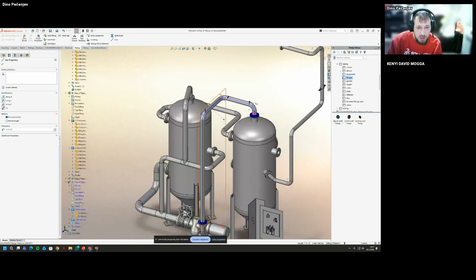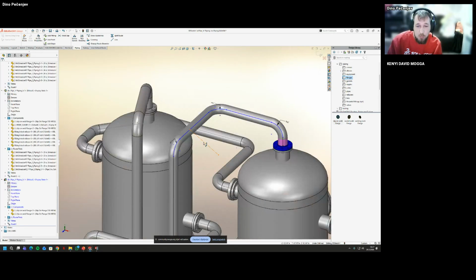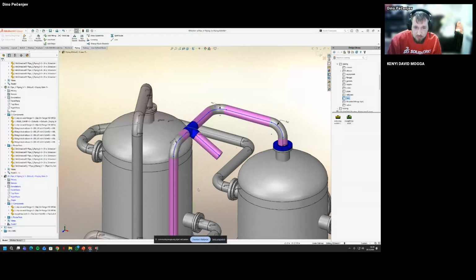So I'm just going to go here and use the front plane and say this is going to be parallel. With this, I can easily control it if I need to put specific angles on the sketch. And now when I drag and drop it, you can notice it takes that point and center line as the splitting part of the route.